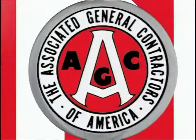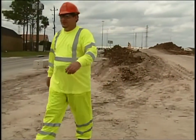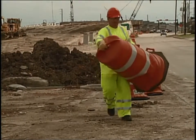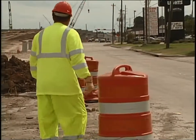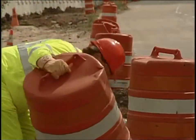Class 3 garments provide the highest level of visibility and are intended for workers who face serious hazards and often have high task loads that require attention away from their work. They are also recommended in areas where employees may be exposed to traffic speeds of 50 miles per hour or greater. Garments for these workers should provide enhanced visibility to more of the body, such as the arms and legs.